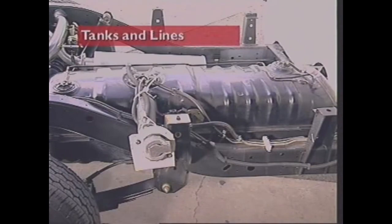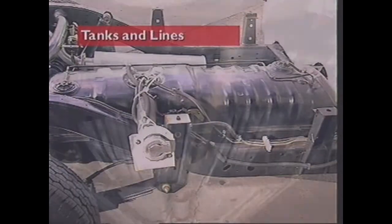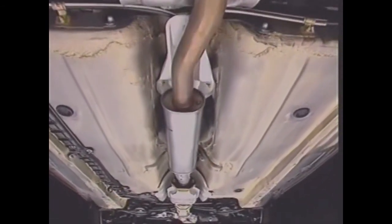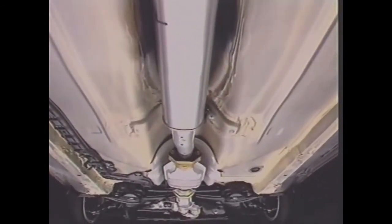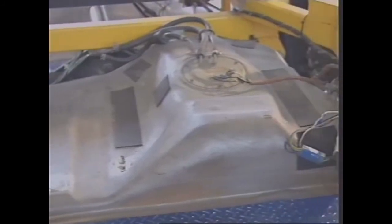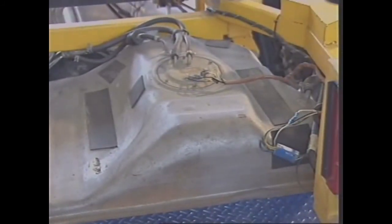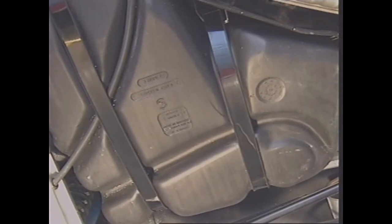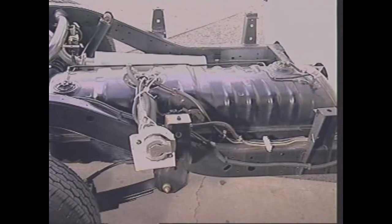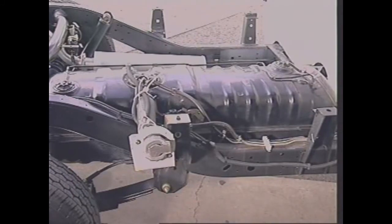This section examines tanks and lines. Where the tank is mounted depends on where the engine is and on space and styling. Safety demands that it is positioned well away from heated components and outside the passenger compartment. Most tanks are made of tinned sheet steel that has been pressed into shape. Some passenger car tanks are made of non-metallic materials. Aluminium or steel is used on commercial vehicles.